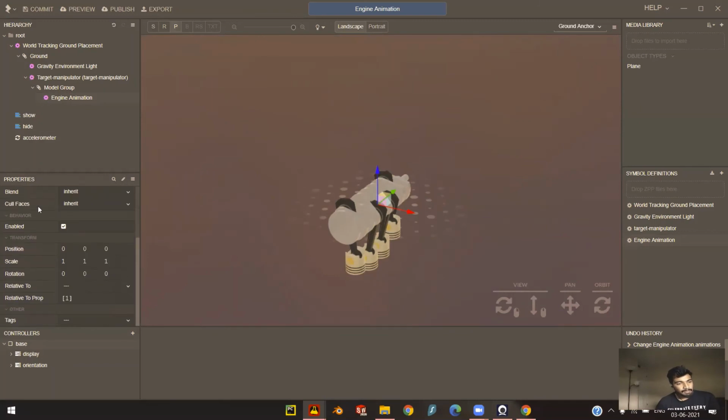So here you will have the transform tab that you can see right here. In the transform tab, you can alter the position of the object relative, and you can scale the object. This is in a 1:1 scale. Of course, you can reduce the scale to 0.5 or whatever you need, and you can rotate. Right now, we're going to have to rotate the object about the y-axis.